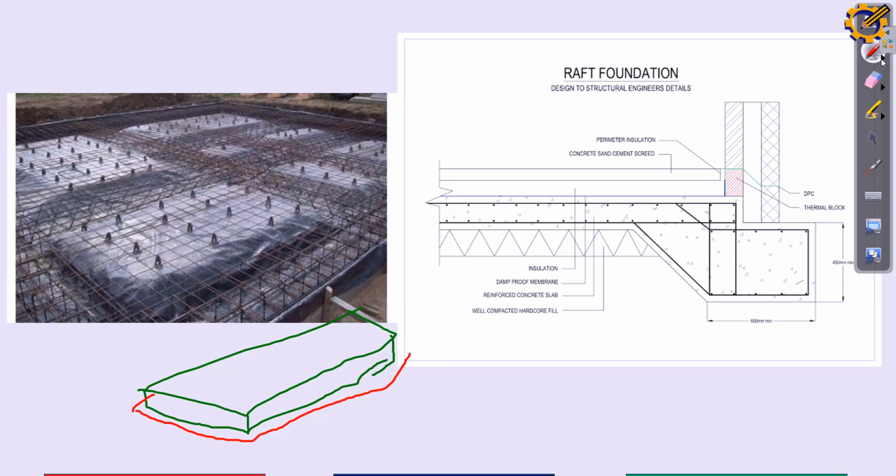Now if rain falls, evaporation takes place, and soil water comes from the bottom to the top. As the soil water is rising, when it gets to this polythene sheet, water can't permeate a nylon, a polythene sheet. So when it gets to this polythene sheet, it will definitely go back to where it is coming from. You don't have any choice than to return. That is because your house actually has a damp proof course or a damp proof membrane.